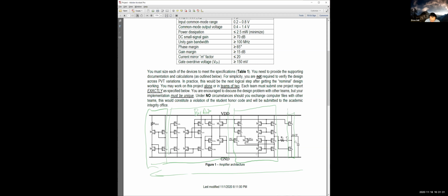When you're analyzing circuits, you usually will go this direction. We'll start with the DC biasing, find all of the operating point, and then do small signal and work backwards. In doing design, you want to start at the output. It's the only thing that you really know. We know about the load capacitance. We don't know much else. And go this other direction. We're going to start with a small signal model. You're going to linearize this circuit and build an equivalent circuit that looks a lot like the one that I showed you on slide 10. Okay. And so there are some design choices that you will need to make.